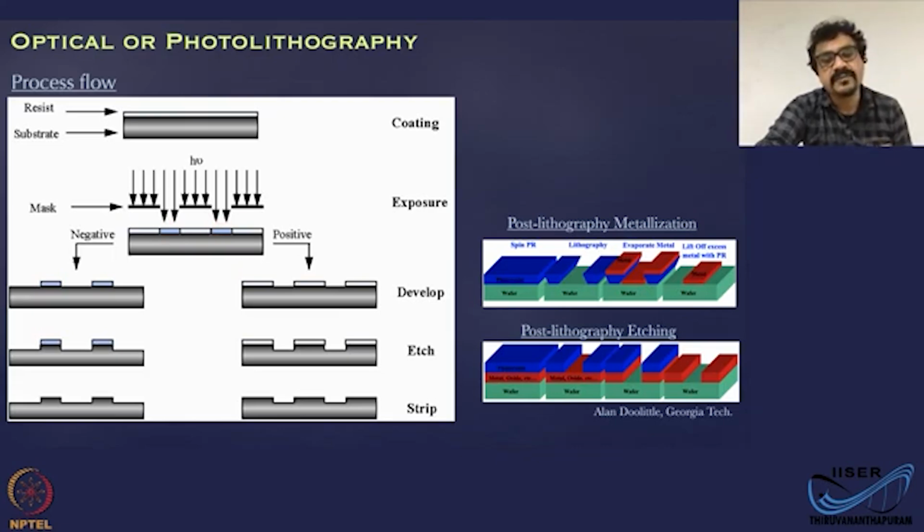Okay. Now, depending upon the type of the resist, you can broadly classify this as a positive resist or a negative resist. A positive resist is something which undergoes a chemical change when exposed to radiation. And the chemical change is such that you can dissolve that region in some other solvent. Basically, you have a long chain of polymer, and whenever the radiation hits the polymer, the chain will break into smaller chains, smaller pieces, and you can easily dissolve that region in certain solvents.